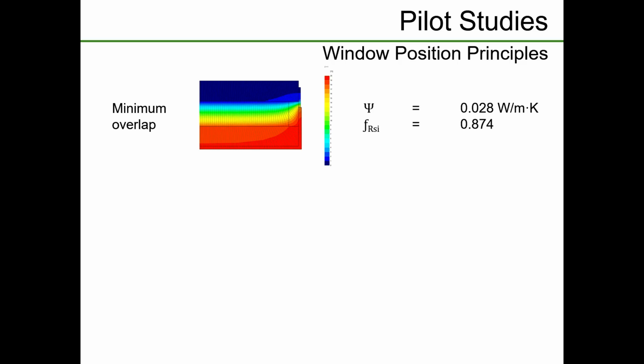What we're looking at here is a windowing plan. This is just to show you the difference that window position will actually make on heat loss. So if we go to the building regulations and use the minimum 30mm overlap between the back of the window frame, which would be here, in the model it's replaced by an adiabatic boundary here, so you're not actually seeing it, but it is there in the model. It's just that we're focusing on the junction. I can explain that later if anybody's interested in the detail of that.